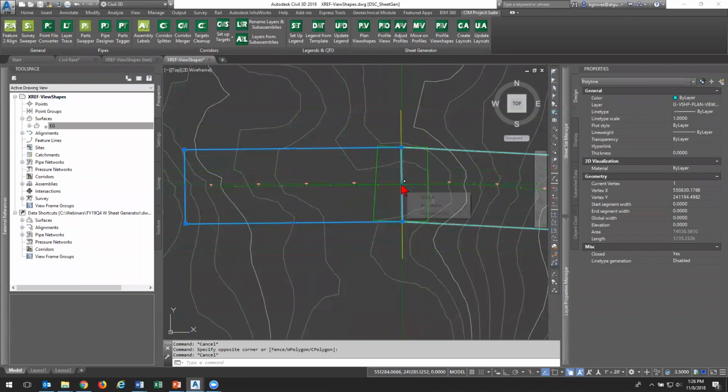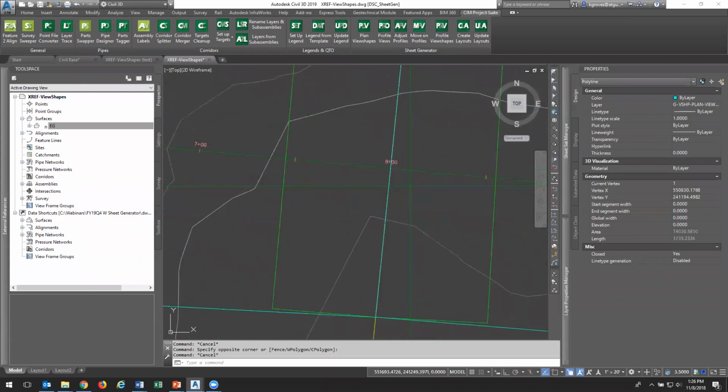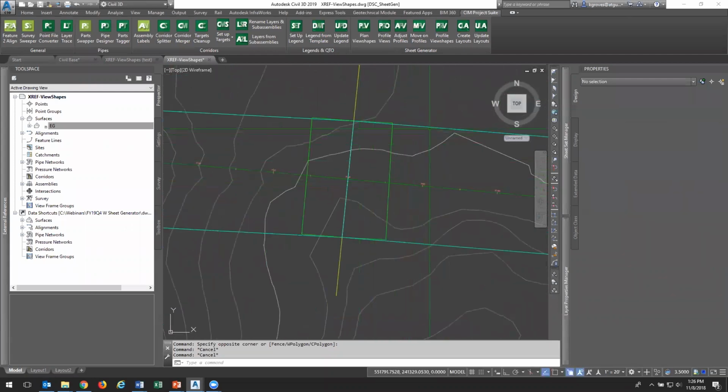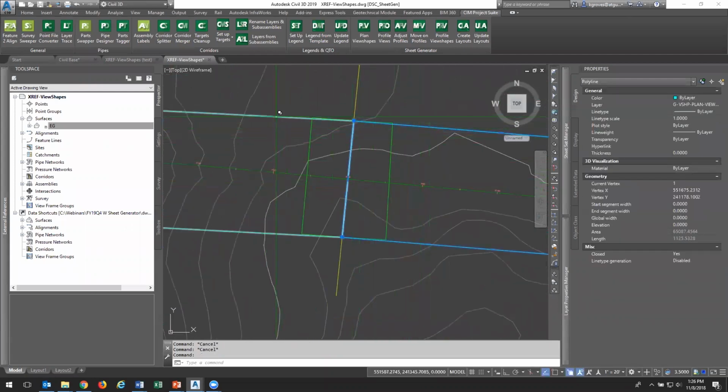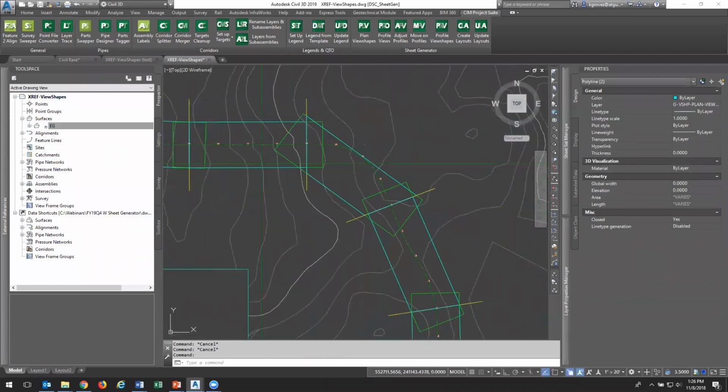And this is what we're left with. So this is what we're actually going to print based off of what we can print. And notice too that since I said round it to a whole elevation, round it to the nearest 100 station feet, all of these drafting guides and therefore all of my printable areas are going to land on whatever interval I specified. We're going to modify this later on, and we'll prove that those do indeed update.